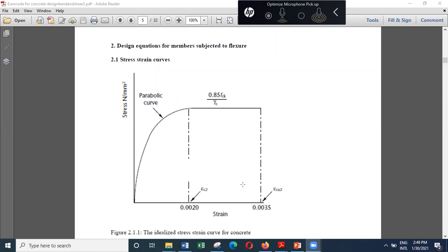But if you have decided to go for a very high strength, then you'll find some of these values will need some adjustment, so that it will take into account the fact that when the concrete is very high strength, all the pores in the concrete are filled up with very fine materials that we use to obtain the high strength. And because of that, the concrete tends to be a little more brittle than the low strength concrete.